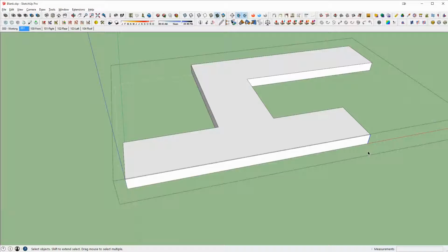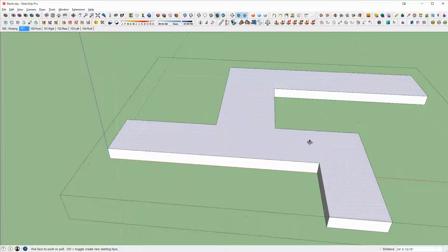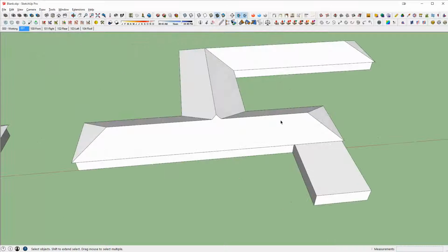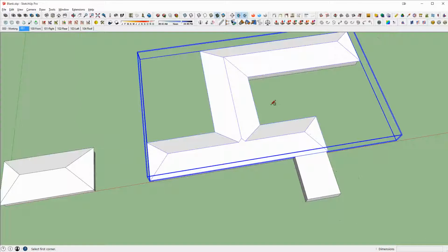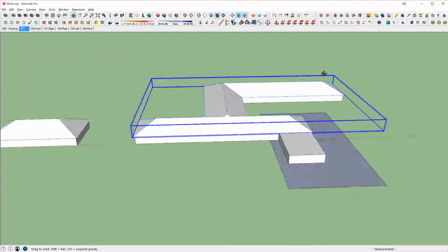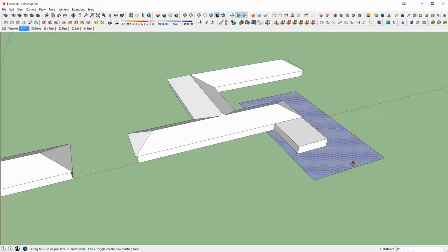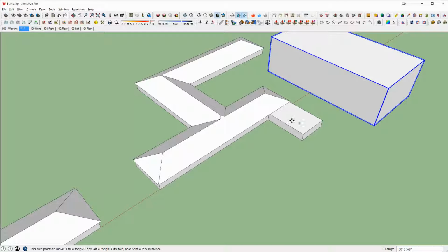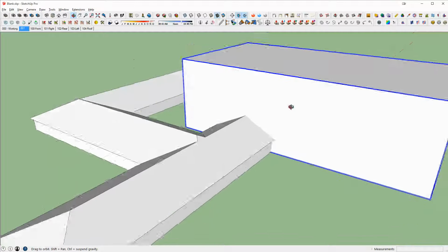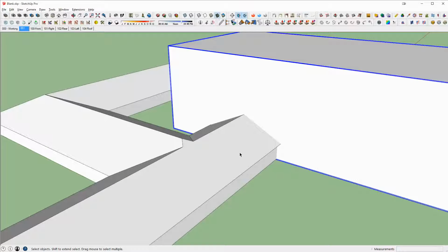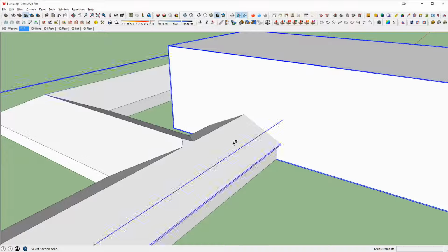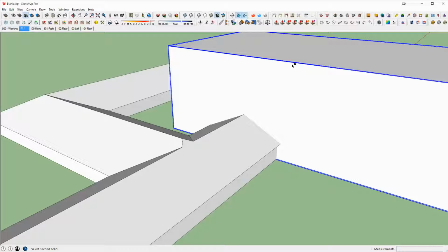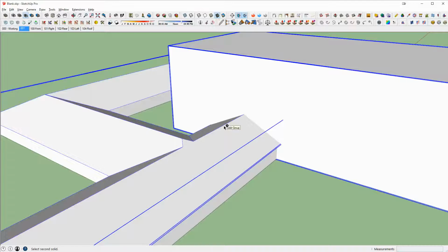Say they came in and we wanted to add this piece on, and we're going to put this extension on so the house does something like this. An easy way to deal with this is we can now draw what I like to call a cutting box. And we're just going to draw a random box, and the important piece is that we are beyond this face because I want to cut this roof. So now, using my solid tools, I'm going to hit Alt V, which I have set up as a hot command for subtraction. This is going to be my cutting box, and I'm going to cut the roof.